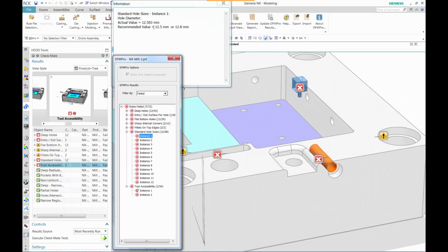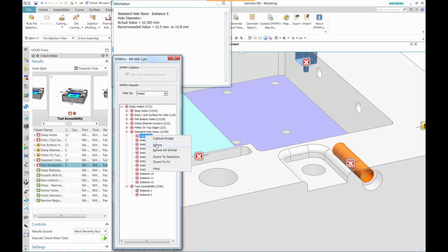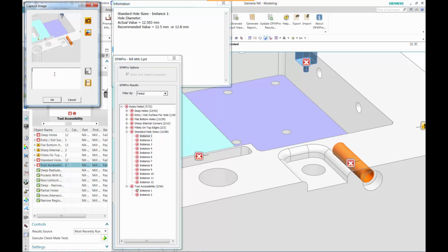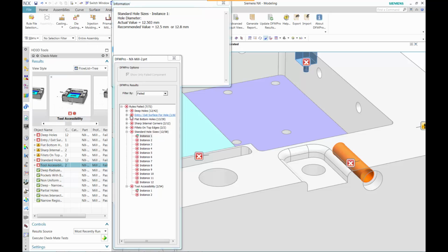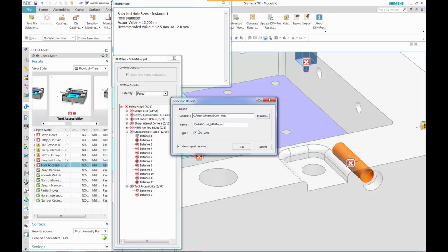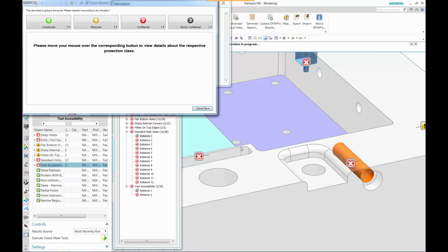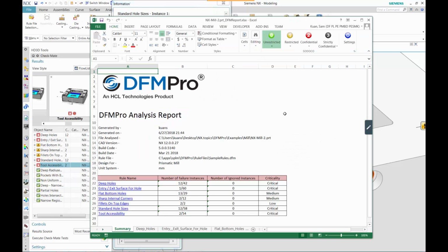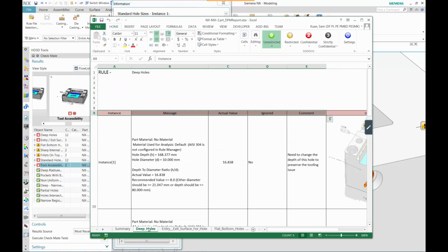if that hole is critical to meet the requirement. The last part we want to do is, in this case, make sure we want to use a standard hole. A standard hole means we're using standard tooling. If we go with a hole specific to the design, that requires unique tooling, and that would cost a little more.